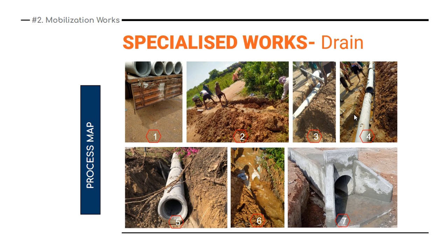So let's understand how the cross connection drainage is done. The best and affordable way is to use hume pipes for that. If you are going for a concrete kind of drain, then it will be costlier. So go for precast hume pipes of around 1.5 feet diameter. Again you need to excavate this area, then lay the pipes and connect them. Here are the connected pipes.